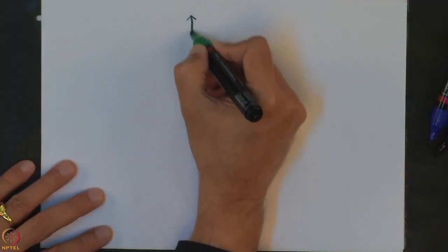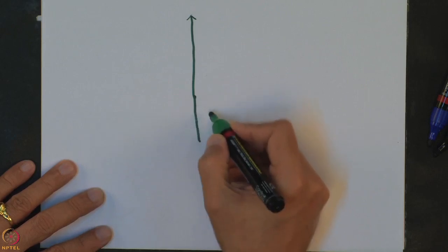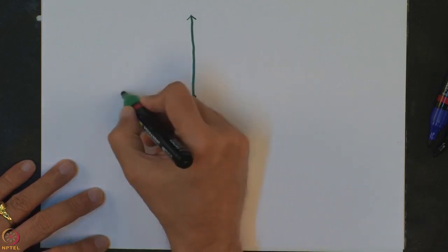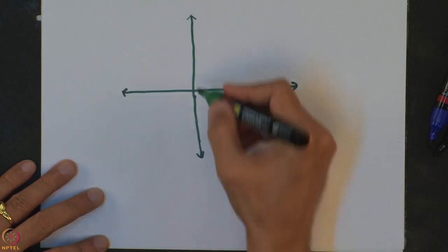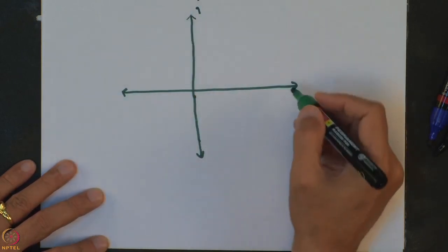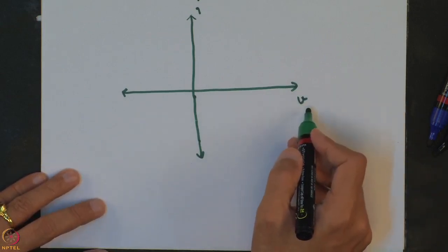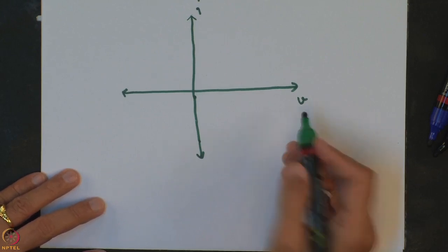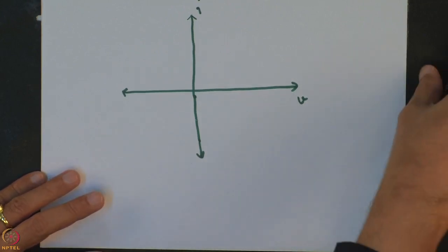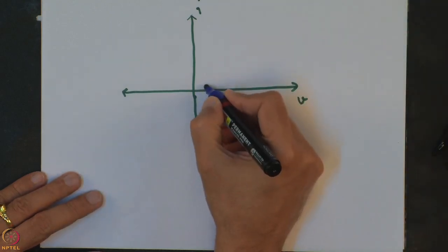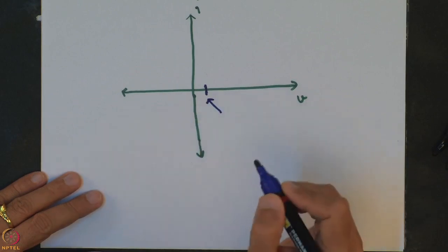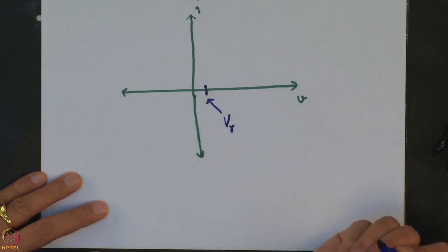The IV characteristics of the diode based on this diode current equation that we derived can be drawn as follows. Let me say this is the y axis, where I is plotted, and this is the x axis over which the voltage across the Pn junction is plotted. In the forward bias case, there would be an extremely small current at first. There is a small cut-in potential here, usually defined by V gamma.